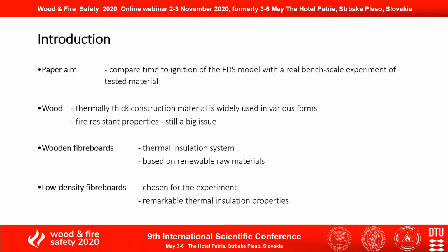The main aim of the paper is to compare time to ignition evaluated in the FDS model with a real bench-scale experiment of the tested material. The tested material is based on wood, which is a thermally thick construction material and is widely used in various forms in different types of buildings, while its fire-resistant properties still remain a big issue.